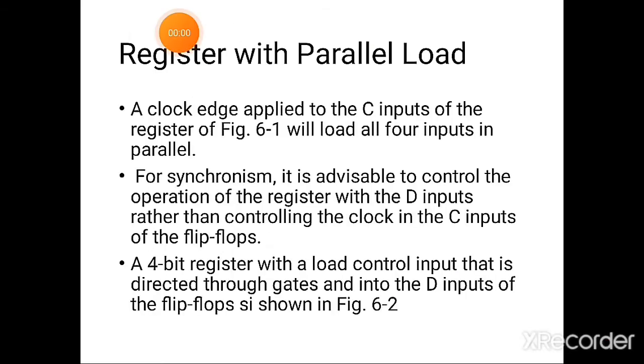Next, the register with parallel load. What is loading the register? Here, the transfer of new information into a register is referred to as loading the register. If all the bits of the register are loaded simultaneously with a single clock pulse, we say that the loading is done in parallel.